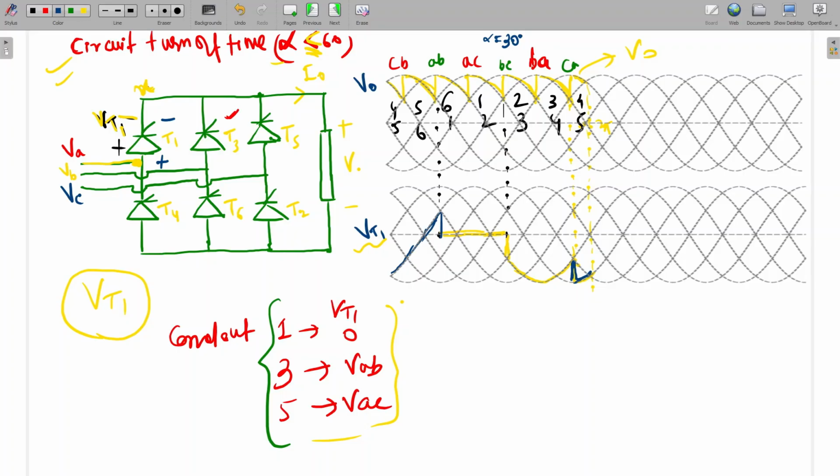Sir, the waveform was explained, sir. The VAB we got, sir, that one. Okay, we see, so thyristor 4, 5 is there. 4, 5 is conducting here after this point. So here to here it is 2 pi, here pi, and up to this point it is 2 pi. So after here 4, 5 is conducting. So when 5 conducts, it will come as VSC.